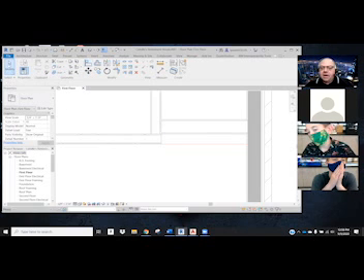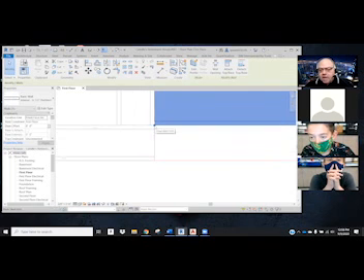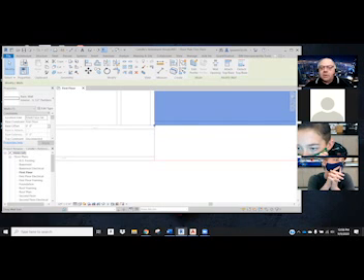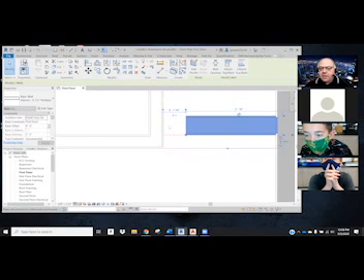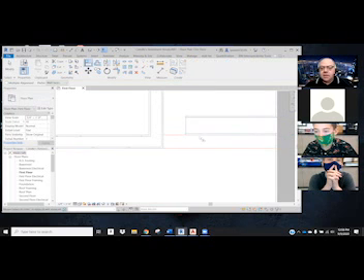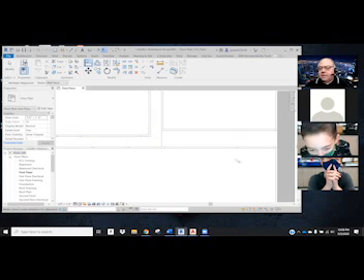Select on the Modify arrow. Select the wall that's a problem. And when I do that, there's these little blue dots. They're like grips. Remember grips in AutoCAD? If I grab that grip, I can slide that over and break that connection. So now there's a gap. Okay. Now when I do the align, it's going to affect that one piece instead of the whole wall. Then I can do a second align and put the gap back in. So it goes really kind of quick to get there. Let's make sure I'm not missing anybody.